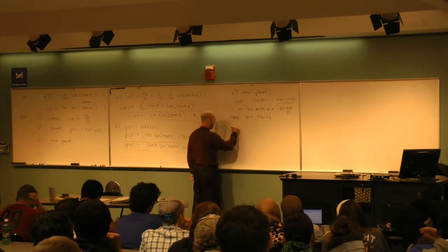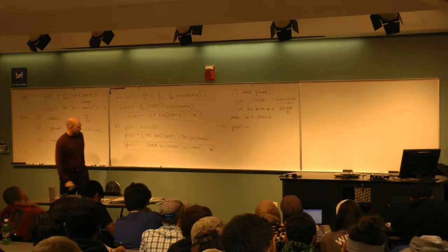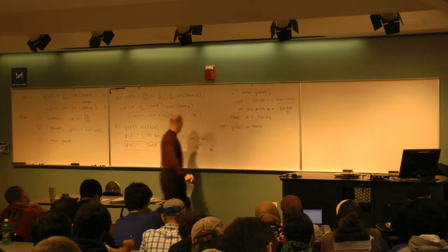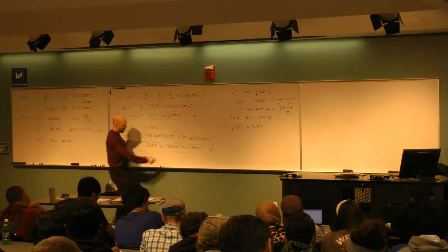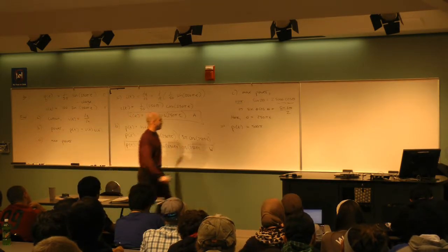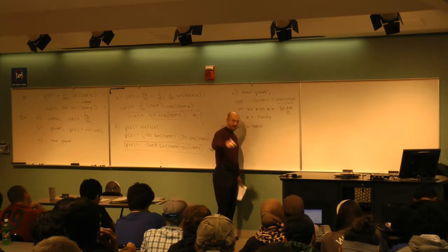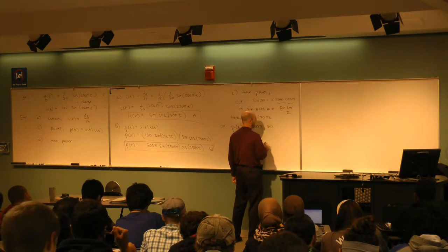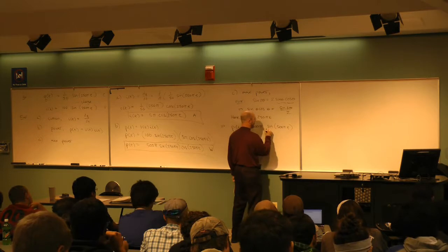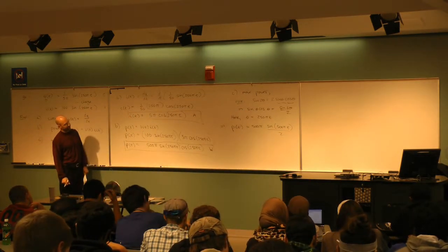So if that's true, then can't I say that the power, again, just manipulating the trig, I got the 500 pi out front still, and I'm going to replace that sine theta cosine theta, where theta is this whole thing, 250 pi t, with the sine of 2 theta. So 500 pi, right? So I'm going to get the sine of 2 theta, 500 pi t, but I got to divide it by 2, right? You guys with me?